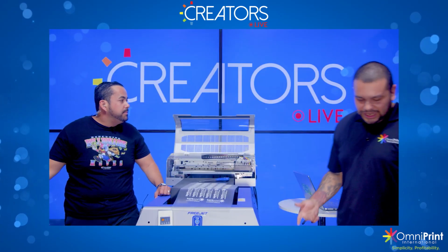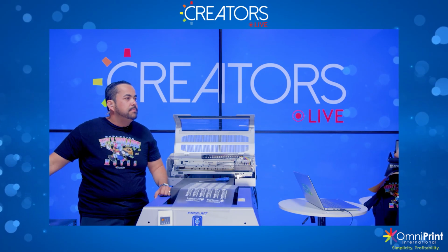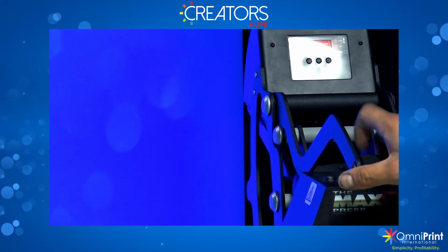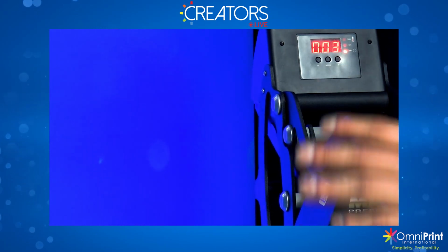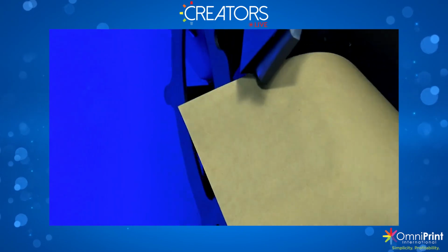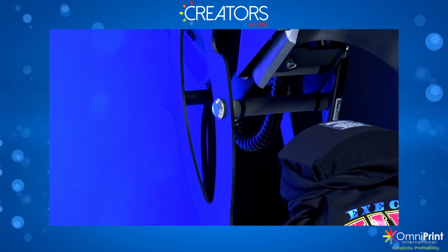Same thing, 15 seconds. We're always going to heat press it for those 15 seconds. And again, always set your time here. I've had guys leave it at 90 and hope they can open it in those 15 seconds, and they walk away, and it will ruin your transfer if it does go over the time. So there it is. This guy's done.